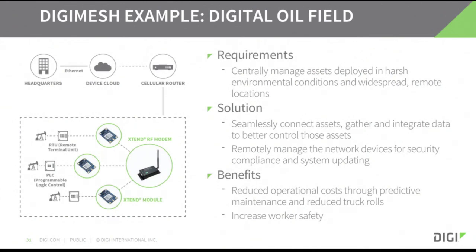And also, Modbus is actually a pretty common protocol that's used in digital oil field applications. And Mark also mentioned this, DIGIMESH works really well with that particular protocol. So in this case, DIGIMESH is a very good fit for this application. Next slide, please.